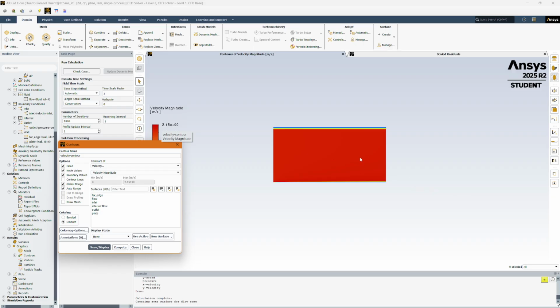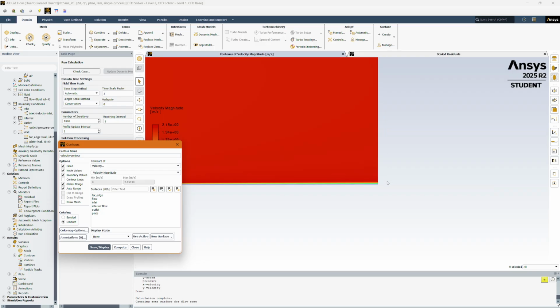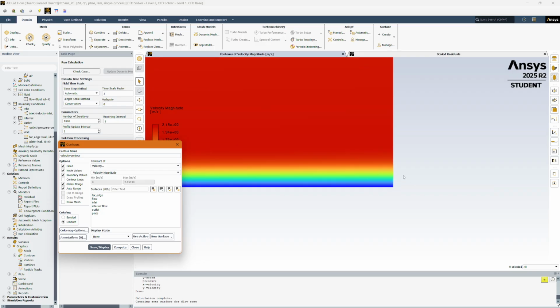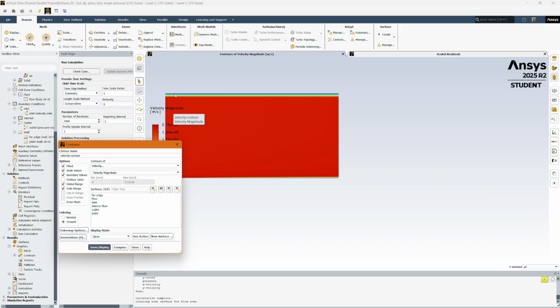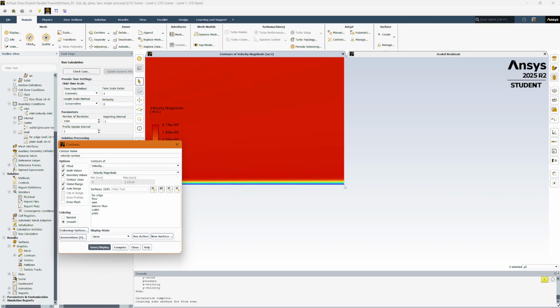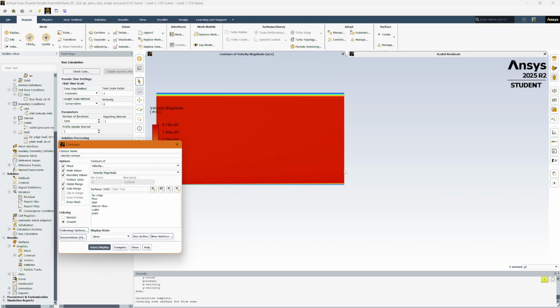And this is actually what we are looking for, because down here we have slower velocity, because the boundary layer interrupts this, because the actual outlet is now smaller than the inlet based off of how this velocity is interacting. This almost gets squeezed like a condenser. Or sorry, not condenser, a converging nozzle. Which actually accelerates us slightly. So that 2.15 is what we were expecting.